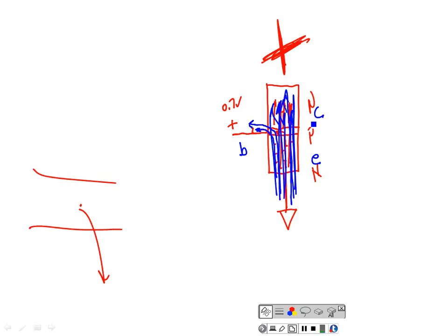Okay. So what we have to do to set the bias is put some resistors in here somewhere, right? It's just like a diode. Let's say I come over here and put a diode directly across the power supply and forward bias it. Somebody's going to give up, right? You understand? Because as soon as I get above the VF of a diode, it acts like a closed switch.